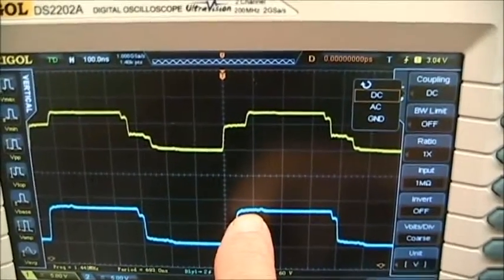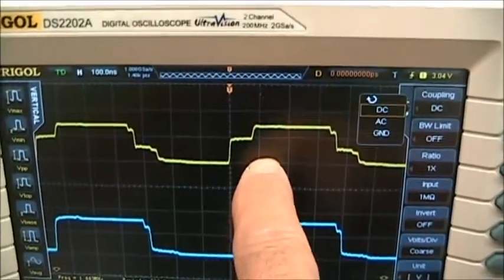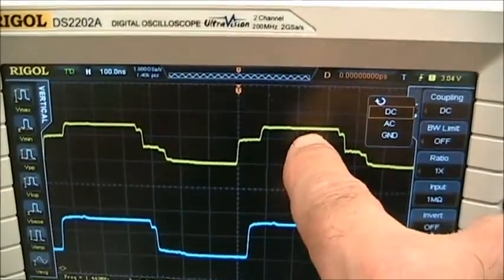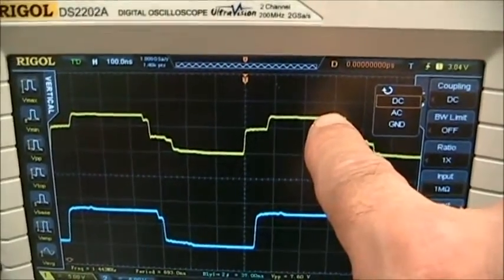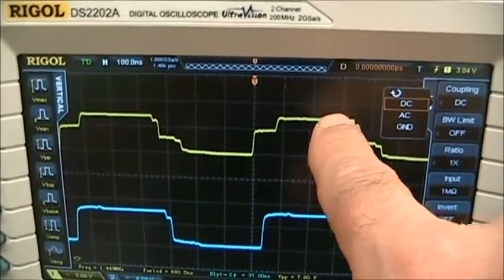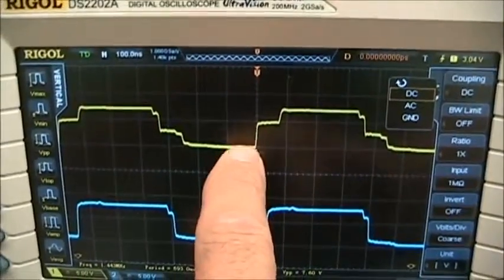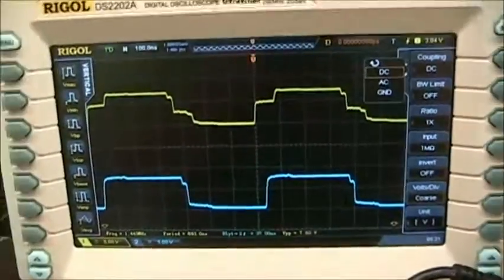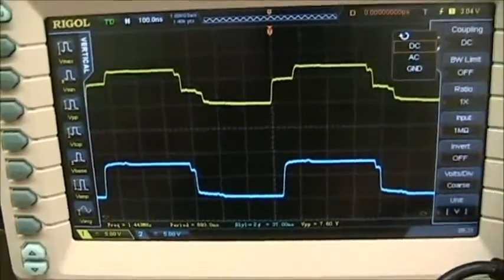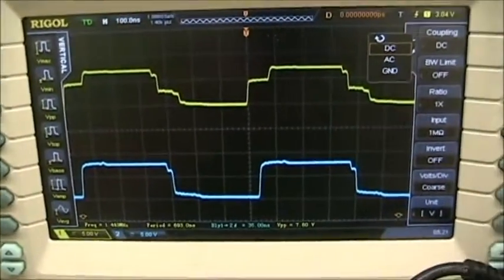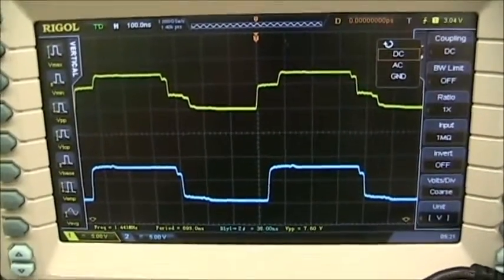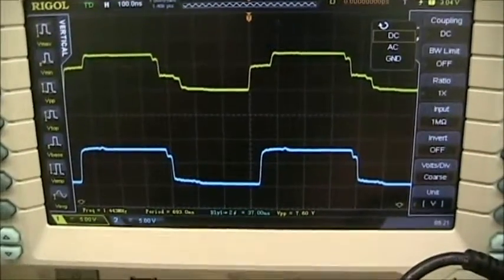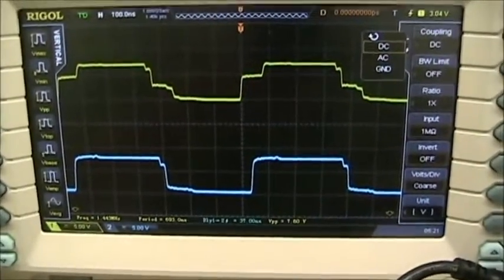It is with a positive gamma value, and then that reflection comes back to the source. Both voltages end up the same at the final value conditions, if you will. But we see the initial pulse travel down and then be reflected back. So we've now looked at a reflection in a match system, a short, an open, a load between a short and a match, and a load greater than a match but less than an open.